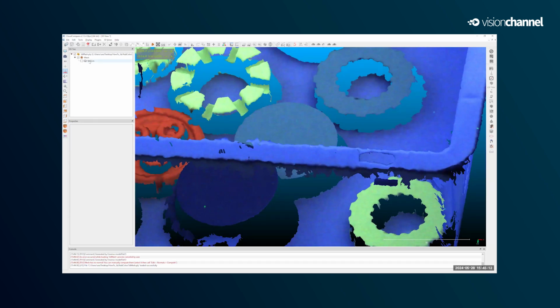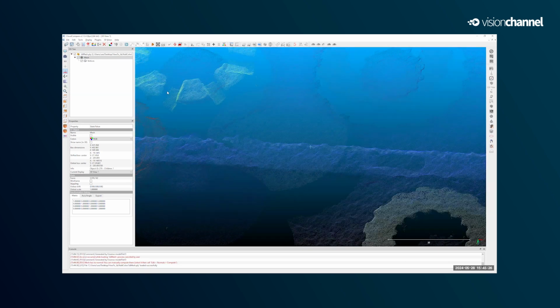In CloudCompare, they are called vertices, or in the PLY file, they are called vertices. So you enable them and you make the mesh invisible, and then you have colored points. So this is the easiest way to save colored 3D data from your Ensenso camera. You just save the 3D mesh as a PLY file.